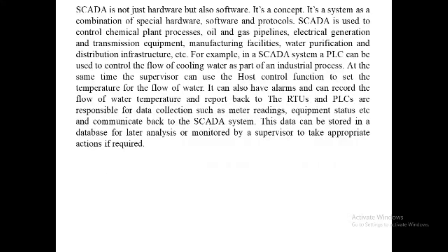A SCADA system typically implements a distributed database, commonly referred to as a tag database, which contains data elements called tags or points. A point represents a single input or output value monitored or controlled by the system.